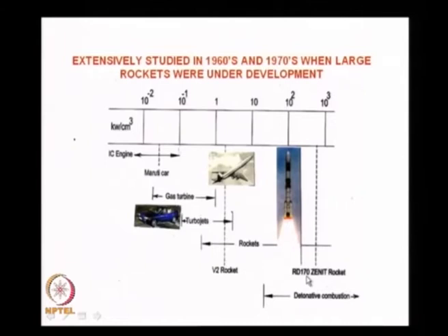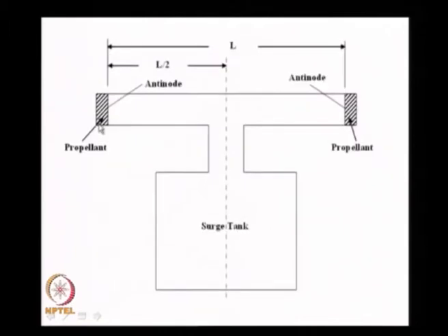We said it burns liquid kerosene and liquid oxygen at a pressure of around 245 bar, and we said this was a very powerful staged combustion engine. The type of energy we are getting is something like 1000 kilowatt per centimeter cube, and whenever we talk of something like an explosion, this is the type of energy release we get. Therefore, even a minuscule amount of this energy, if it gets into the wave mode, I could start getting oscillations. To figure out how much of the heat release gets into the oscillation, we have specific devices. Now, this is something which we must know.